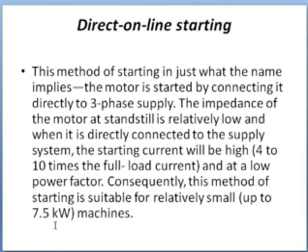So this methodology is applicable for low wattage motors, because a low wattage motor reaches steady state speed in a very short time, so the back EMF is generated quickly and the starting current is reduced very fast. That is why the direct online starting methodology can be used.